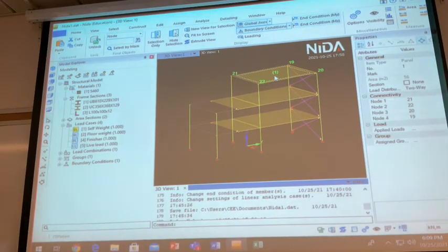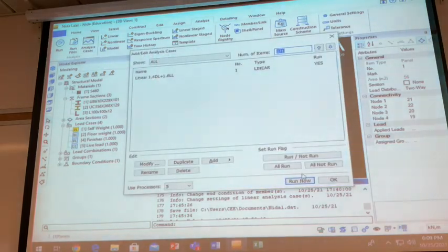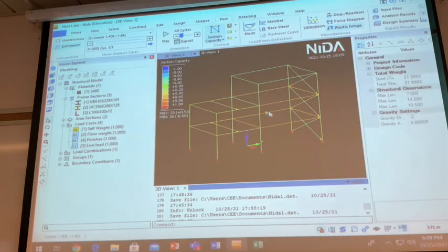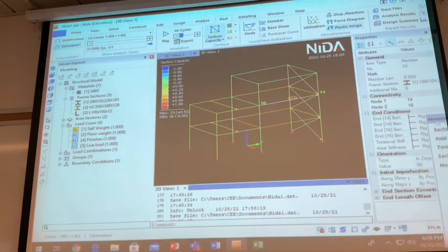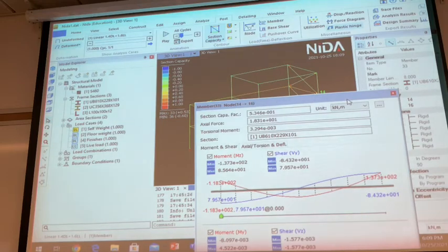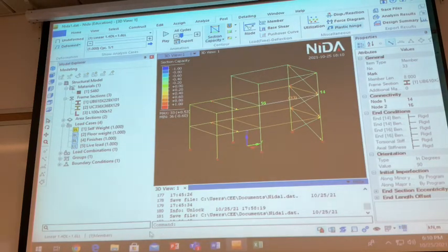Anyway, I want to tell you, you have two ways to get the loading for this. You will want to check the loading. You just double click the member you want to check. So you have all the moments and then the CR4. That's enough because you just have one load case. If you have many load cases, then I prefer you use Excel. Okay. Now, finally.